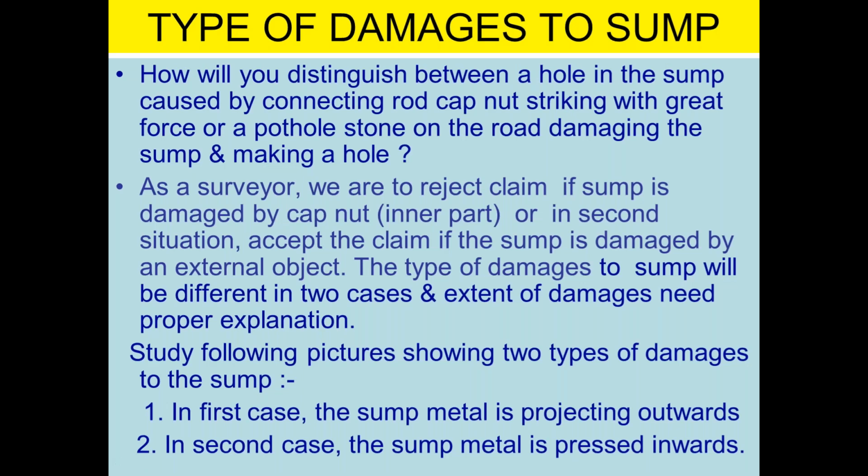Type of damages to the sump. How will you distinguish between a hole in the sump caused by a connecting rod cap nut striking with great force, or a pothole stone on the road damaging the sump and making a hole? As a surveyor, we are to reject the claim if the sump is damaged by the cap nut from the inner part, or in the second situation, accept the claim if the sump is damaged by an external object. The type of damages to the sump will be different in the two cases, and the extent of damages needs proper explanation.